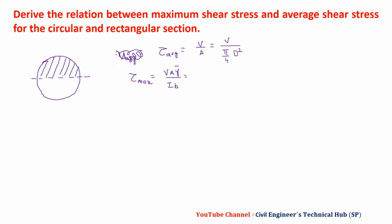Now we will consider a small portion of this, and then we will consider y bar. So what we will get in this y bar, let the width we will consider as b. So we have considered this b, and we will get it as 2 root r square minus y square.